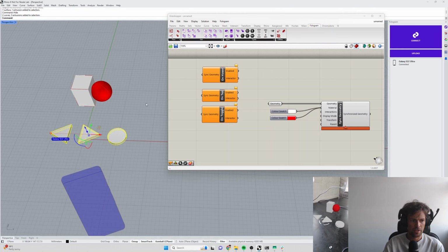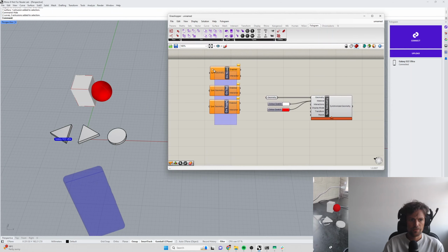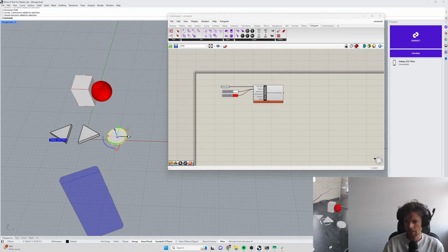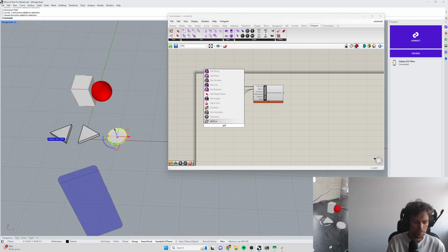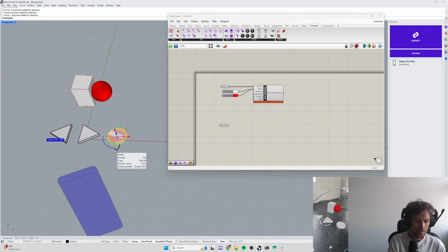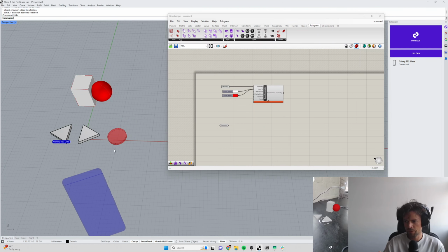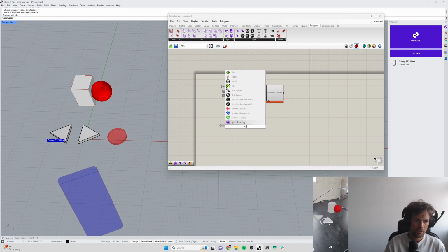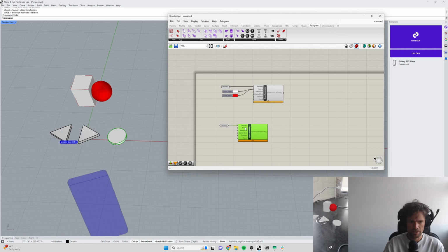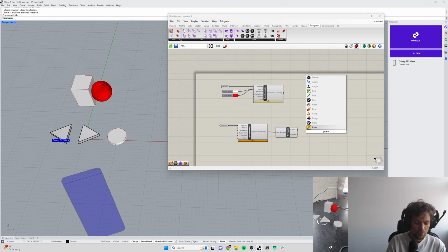And then we have this UI here in Rhino. Now I'm going to get my button, which I'm going to use this disk here as a button. So let's reference that in with a geometry parameter as well. And then again, we can hide this from Rhino because we don't want overlap, we don't want to synchronize the same geometry from Grasshopper and from Rhino. And we'll sync that geometry as well. And then it appears again in mixed reality. And we'll use an on toggle component with that sync geometry to detect taps